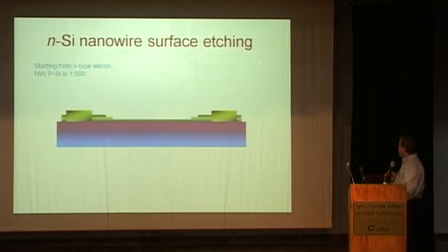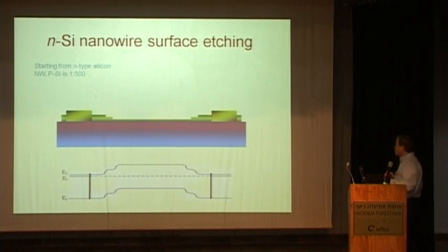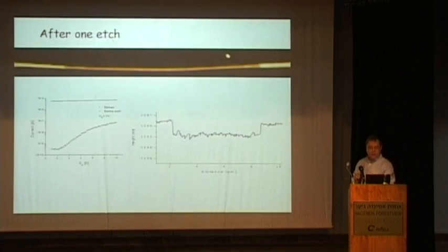And if we measure it with a Kelvin probe force microscope, what we will actually measure is this profile here. This is the Fermi level, which is constant, and going from right to left, we will measure this profile because the wire is more heavily doped in the circumference, and as you go into the wire, it's less and less doped because of diffusion, if the diffusion of dopants is strong. And you will see this in a measurement in the next slide.